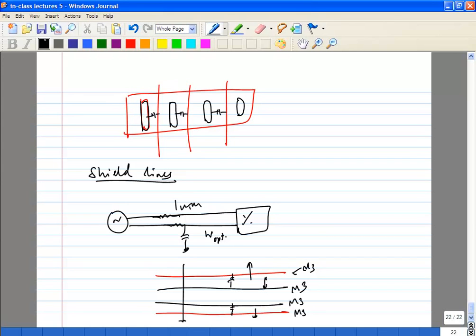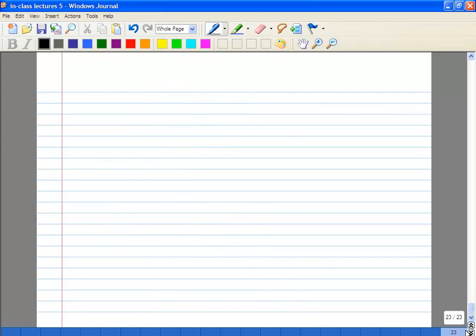Second thing, you can use it on as far away a metal layer as possible. So if this is on M3, you either want to do it on M6 or on M1, depending on the signal. You may not be able to do it on an immediately adjacent metal layer; we'll add extra cap. Next we'll look at substrate contacts.